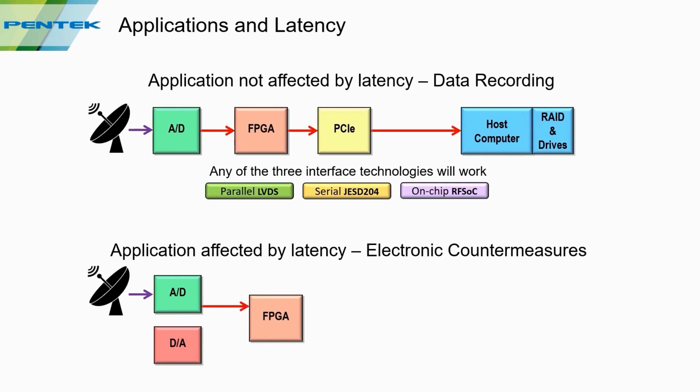Now in this case, the FPGA needs to process that signal to modify it to look like a return signal from a plane that's maybe further away or traveling at a different velocity. Basically, something to make sure the ground targeting system can't get a fix on your position. Then it needs to transmit that signal back to appear to be the bounce of the original radar signal. And this has to be done quickly and with a determined latency.